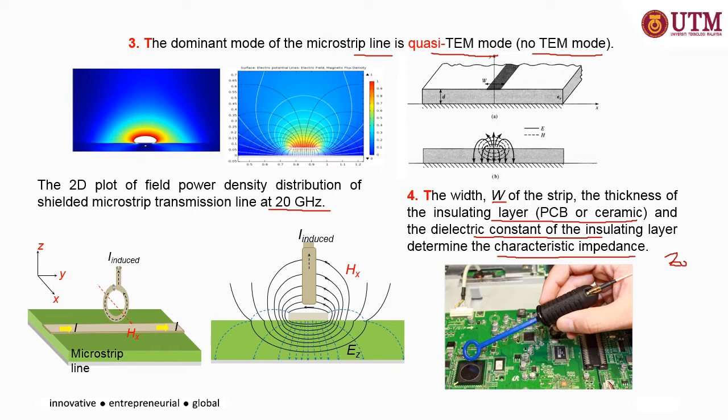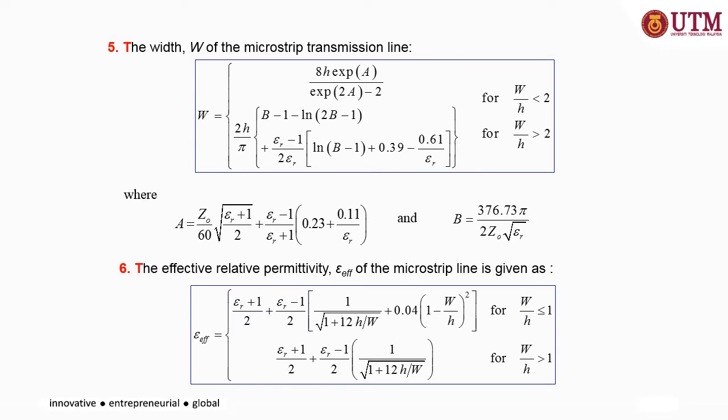Okay, basically in the design process, you need to properly determine the width and the thickness of the microstrip line, because it will control how the field propagates, what frequency it is suitable for in the targeted application, and how about the radiation, etc. The slide summarizes the equations related to calculating the width of the microstrip line, which include the thickness h, the relative permittivity, and so on.